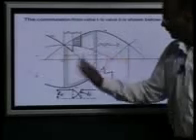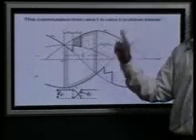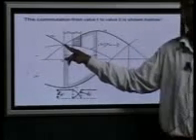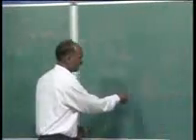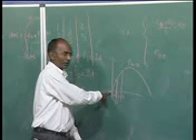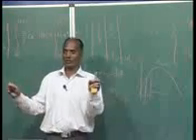So if you are starting from here, then you have to take the phasors accordingly, but we took EBA as our reference. EBA reference was 0 here, because I took EBA as the reference at omega t equal to 0, as these are phasor voltages.